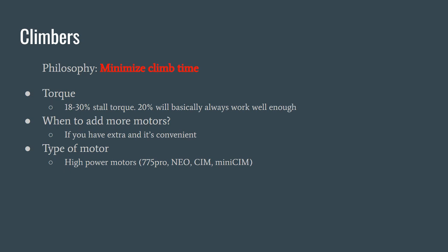If you're making a custom gearbox, you have to be more vigilant. But if you're just doing what we do, which I think is a good policy, just throw something on there with the VersaPlanetary and change it if you need to. Just do the calculation, get close, and then figure it out from there.